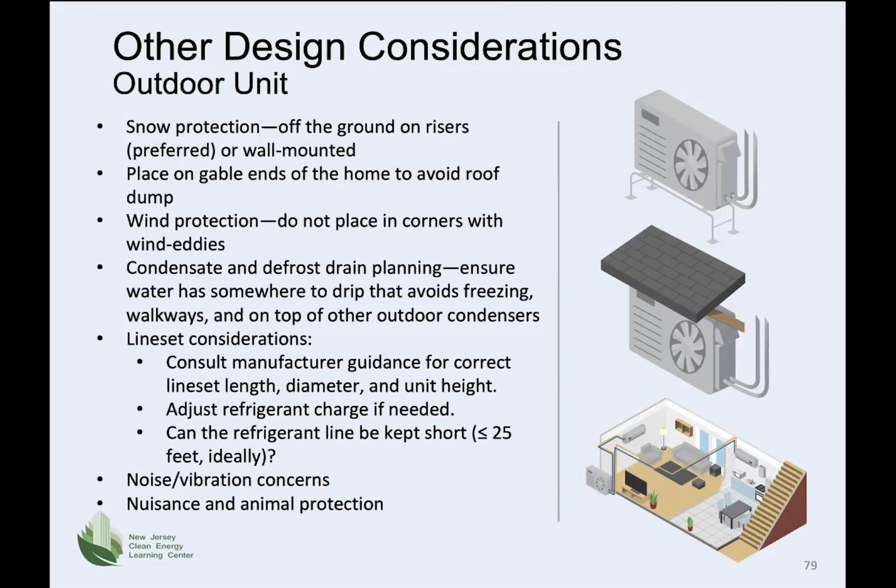As far as the line sets are concerned, part of this is going to be a function of how big the house is and what your overall strategy is for servicing the heating loads. But the line sets in general want to be kept to a minimum. So you want to consult with the manufacturer about their particular unit and what the maximum line sets are and what the diameters should be.